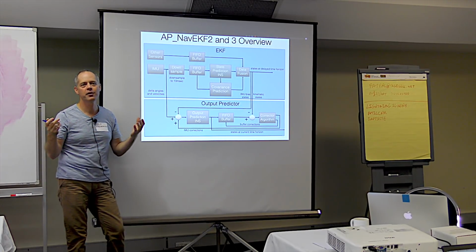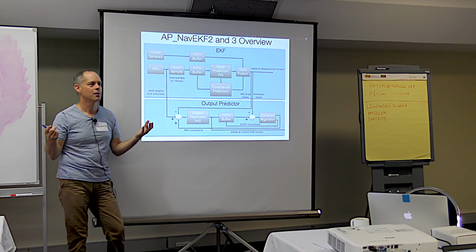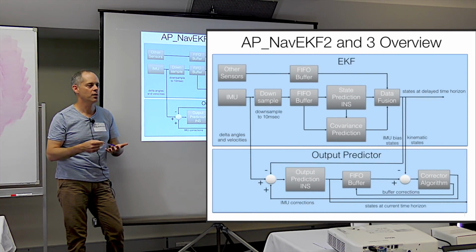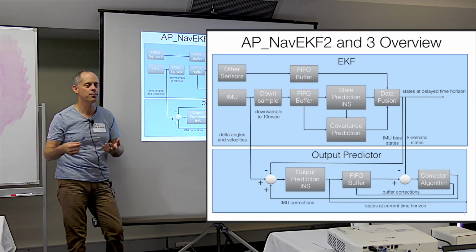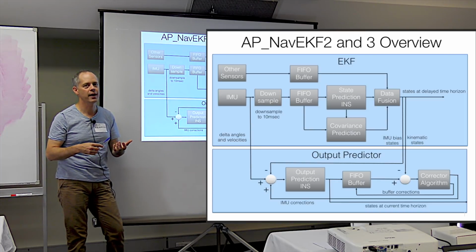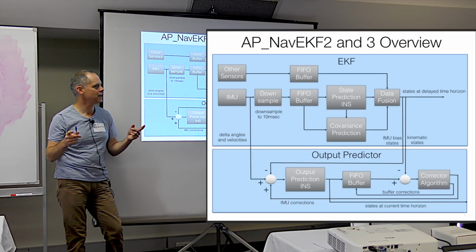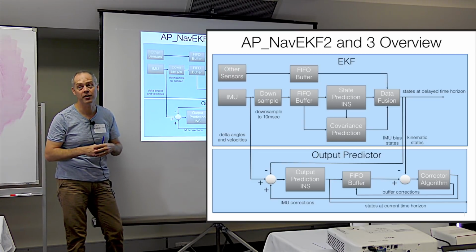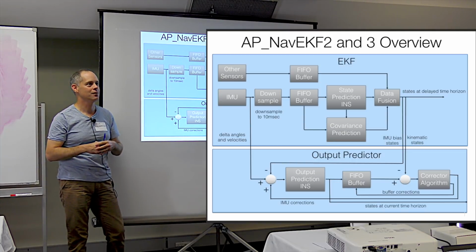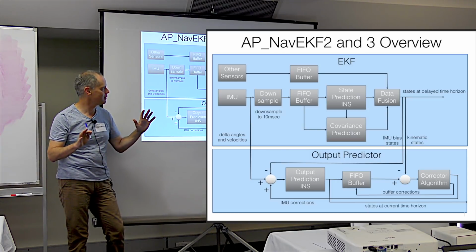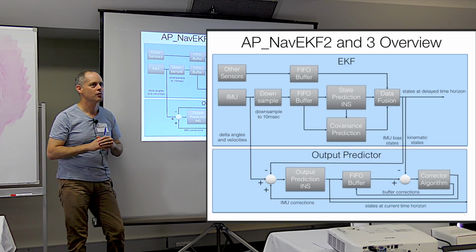That means for those of you integrating off-board sensors like SLAM or visual inertial odometry, or a different model of GPS, for example, if the timestamping is incorrect, it can have two effects. It can introduce errors, but if the timestamping error is very large, the EKF will basically not use the data at all, because the data gets overwritten in the buffer before the EKF gets to it. So that's a couple of points to bear in mind when you're thinking about quality of sensor data.